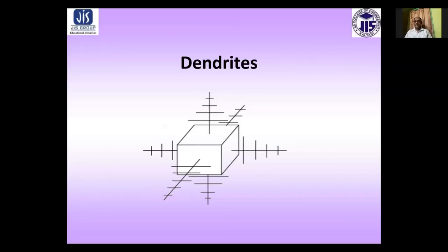A considerable amount of latent heat is evolved in the direction of crystal growth, causing the temperature of the adjacent liquid to rise. This temperature may exceed the freezing temperature of the metal, so that further growth of the crystal in this direction will be stopped.